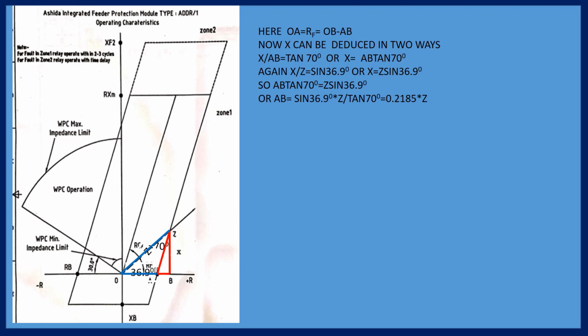It is very important. In the field also, if you don't earth the mast with the structure bond and your insulator has broken, then the current will leave to the surface due to short circuit. When the insulator breaks, the current will come to the mast, and the foundation concrete is not a good conductor.